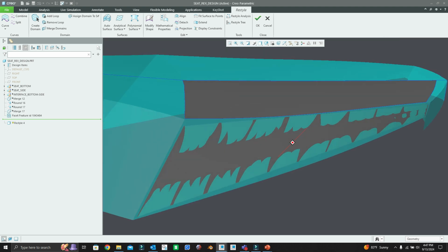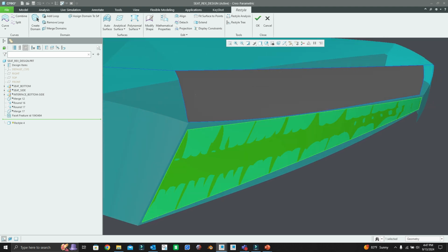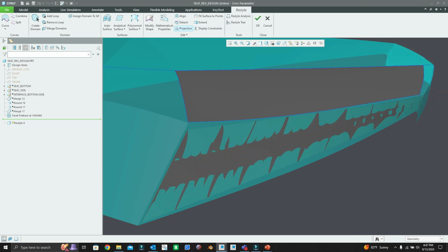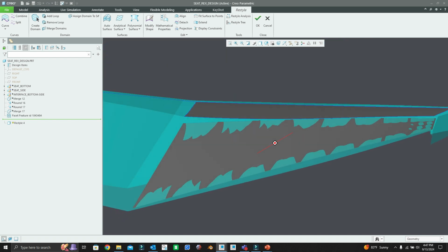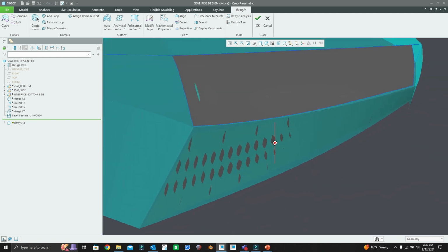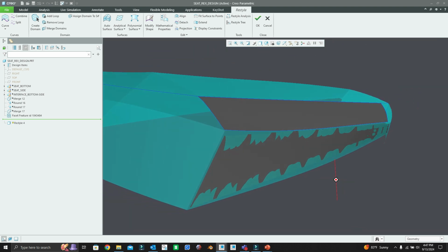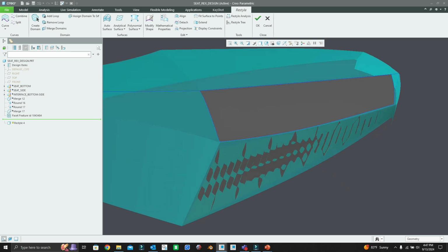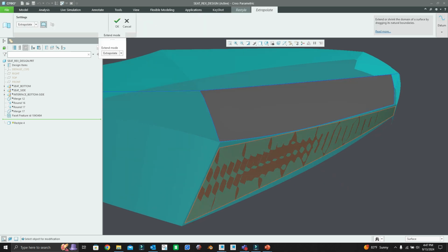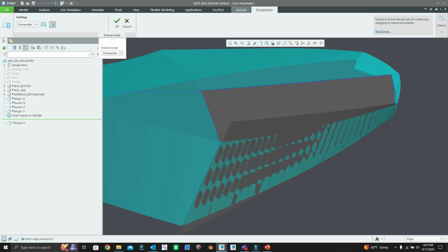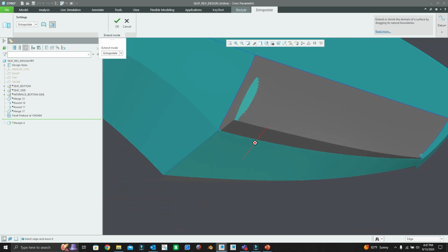Okay, now what's great about using this surface creation method, let me reduce these first and project. The great thing about this surface creation method is it allows you to easily extend the surface within the reverse engineer or within this freestyle tool. So with the extend option, I can take this surface, select it, and extend that side out and extend this down further if I want to.